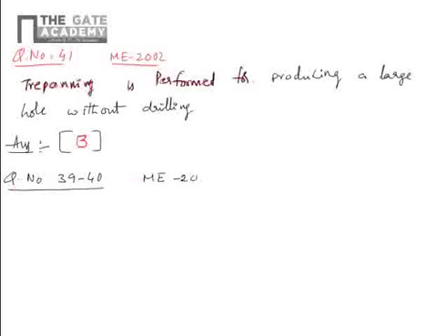2003, 4 marks question. A cylinder is turned on a lathe with orthogonal machining principle. The spindle rotates at 200 rpm. The axial feed rate is 0.25 mm per revolution. Depth of cut is 0.4 mm. The rake angle is 10 degrees. In the analysis, it is found that the shear angle is 27.75. Calculate the thickness of the chip produced.